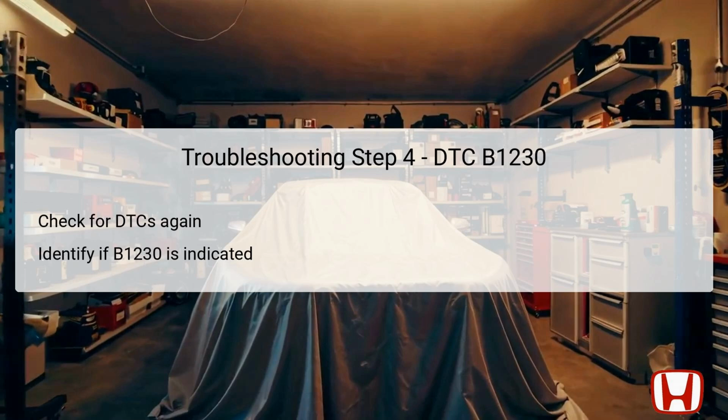If the code is indicated again, this suggests that the issue remains unresolved and further investigation is necessary. Conversely, if DTC B1230 does not appear, it may signify an intermittent failure, likely caused by a loose connection or a temporary fault. Regardless of the outcome, this step is critical in guiding the next actions.